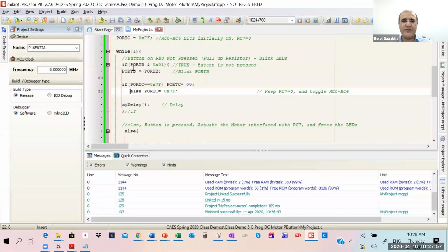Imagine if you want to read the peripherals. The push button here is a peripheral. This way, if it's pushed, do this. Then if something else is pushed, do this. Then if the temperature equals X, do this. So if you are here and something up there happens, you're not going to know about it until the program counter goes back. And this is called polling.